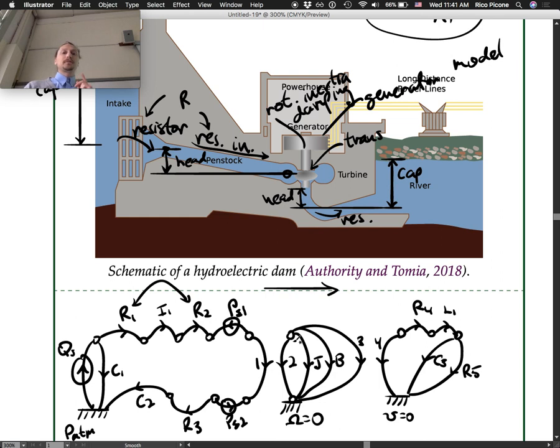Yeah, so the mechanical system is pretty simple. It's just a rotational mechanical system. It consists of a shaft, some bearings, and some inertia that turns. You're probably going to be turning a rotor that has some significant inertia you need to take into account. It's really just one rotational speed besides the reference of 0, so 1 omega.